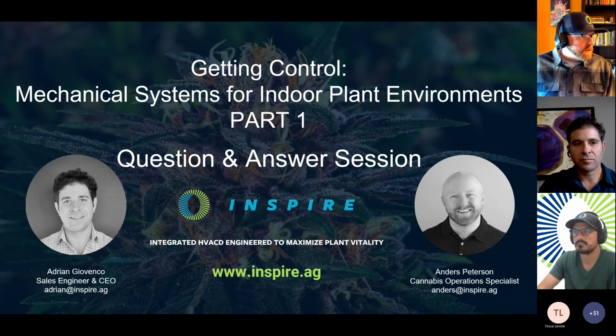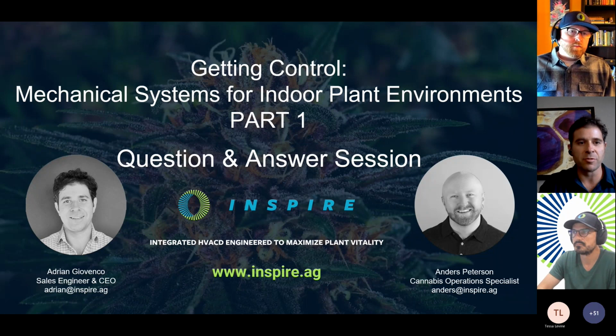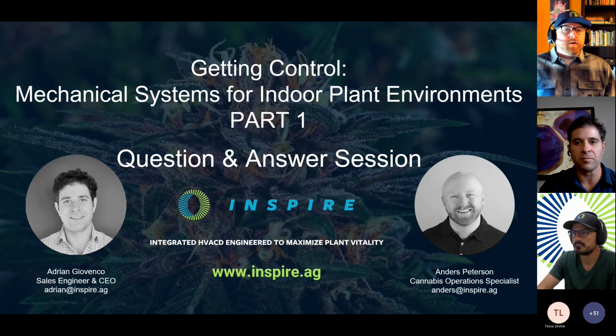Then, Nate, you want to talk about the lights and the driver losses and stuff? I guess I'm assuming this is suggesting that the drivers would be mounted outside of the cultivation space. If that is indeed the case, then we can take that percentage off. What are we talking about? 10 to 15% potentially of that overall heat load could be moved outside of the space.